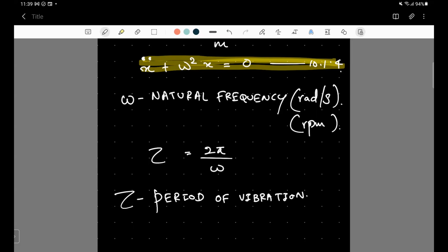So the damping results in natural circular frequencies that are smaller than that of the undamped system. The maximum displacements are also smaller when damping occurs. Whenever there's damping, the maximum displacements are smaller in such instances.